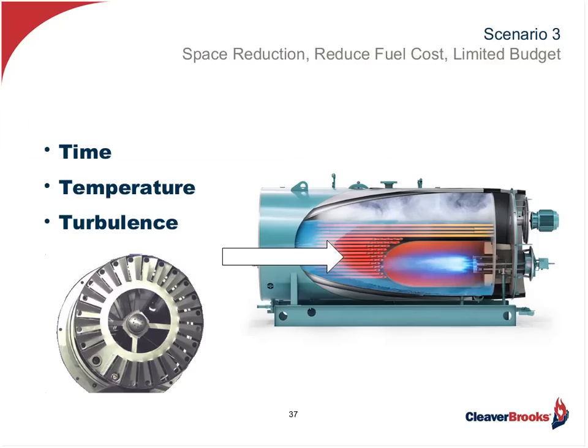Now, as far as the burner is concerned, that also has to be looked at very closely because it has to be matched properly to the furnace that it's firing into. And of course, you all know that for combustion to be complete, you need time, you need temperature, and you need turbulence. Well, as far as temperature is concerned, that's formed by the chemistry of the combustion process. You start with a spark, it lights a pilot, you then light the combustible mix, and from there on in it's spontaneous, the chemical reaction of combustion. That gives us the temperature.